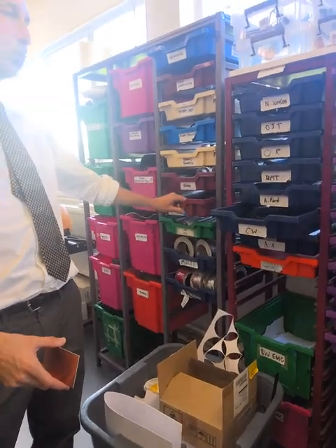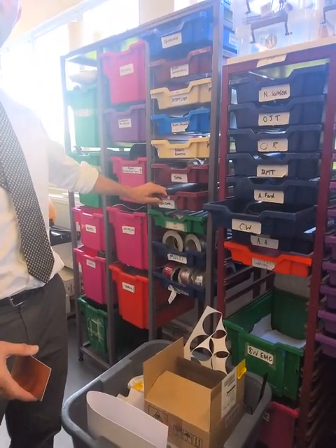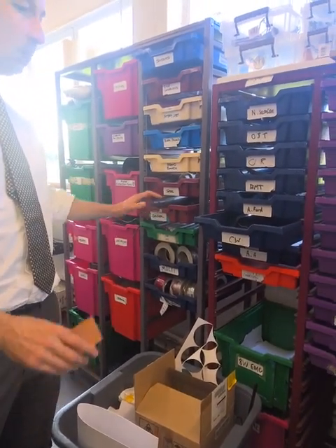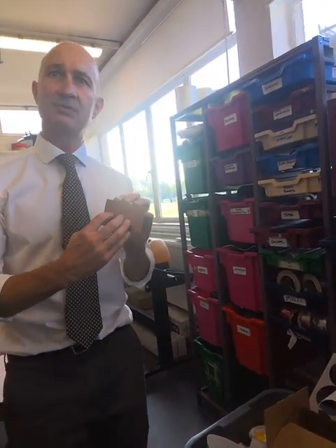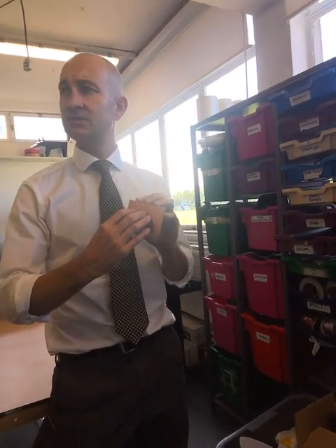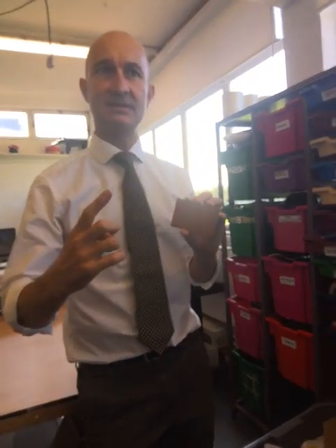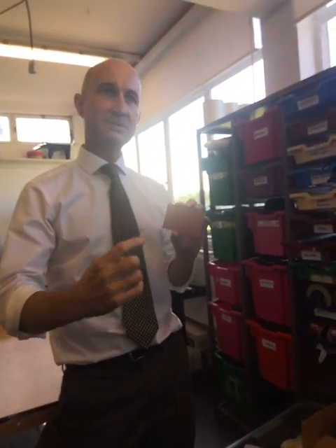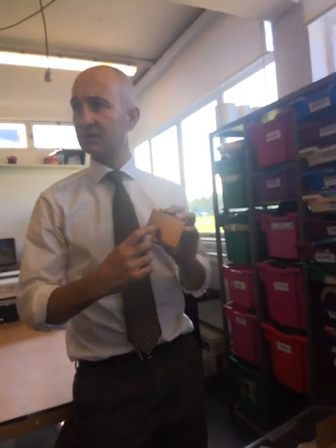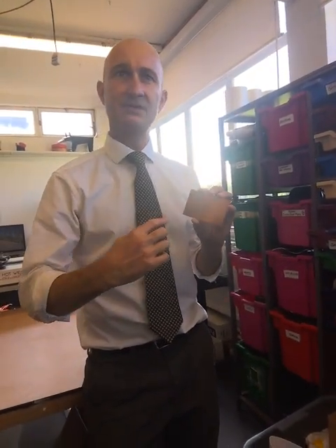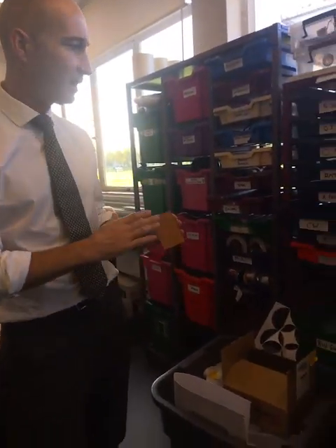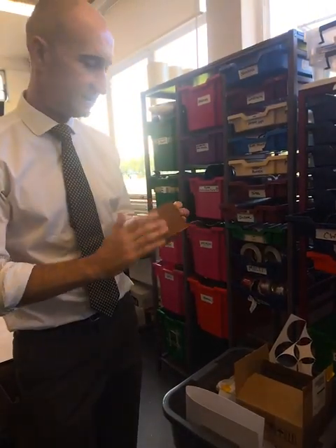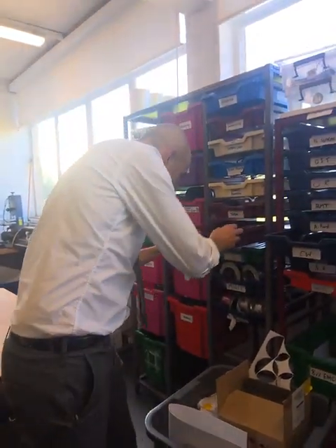Usually over here we have a tray which has wire wool in it. It should be labelled with wire wool in it. What you have is your copper tracks, but what's on top of the copper tracks? Oh, the film, that photoresist, and that's a plastic. So if I was to put a component onto that, try and solder onto that, I'd be soldering onto the plastic. So we want to get rid of that. The way we get rid of that is we get another piece of wire wool and we just go over the surface, and it's a shame there's none here.